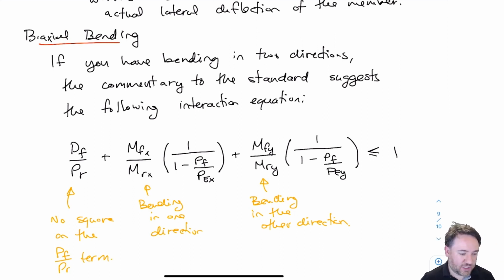Since we have bending in both directions now, it's no longer clear how that difference between compression and tension is going to affect the section, because I could be applying tension from bending in one direction, and then in the same place applying compression from the other. So it's really just the net tension that we're checking against here. So when do I reach that total tension strength, including consideration of amplification for P delta effects.